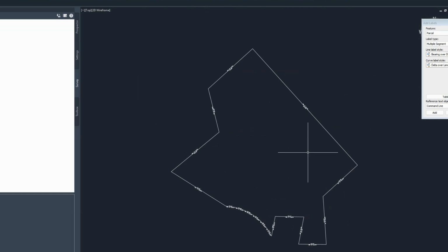If we can identify where this road is, where this school boundary is, maybe there are fence lines, we can fit this to that, and then we could extract coordinate points, x, y, lat, longs, that we can use to stake out and guide us to where we're expecting to recover some of those original monuments. And if you're doing this survey with a GPS instead of a total station, that's going to save you a lot of time and having to COGO this in the field.